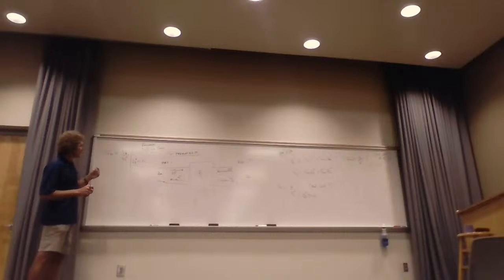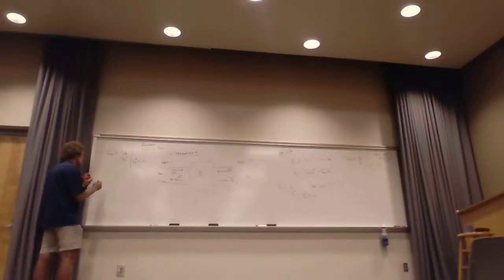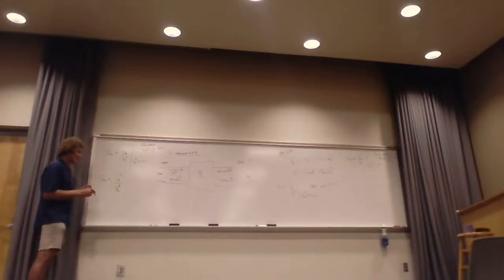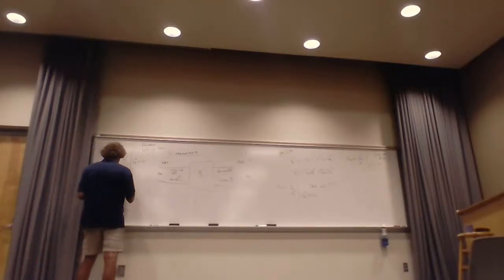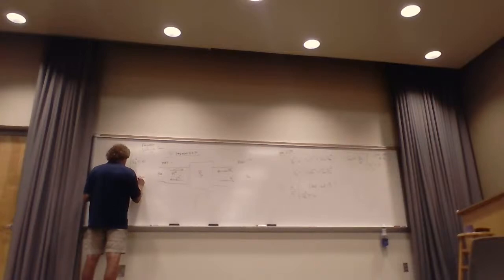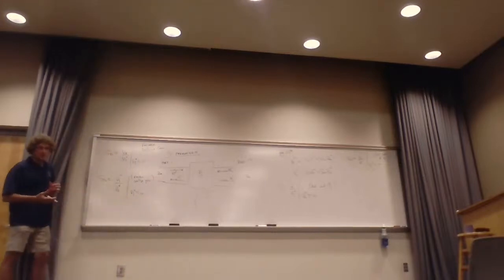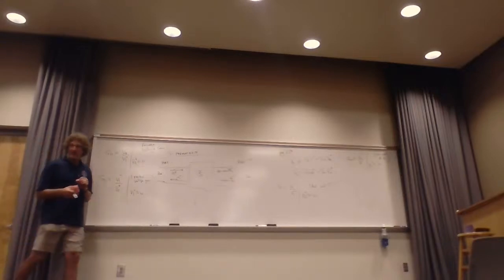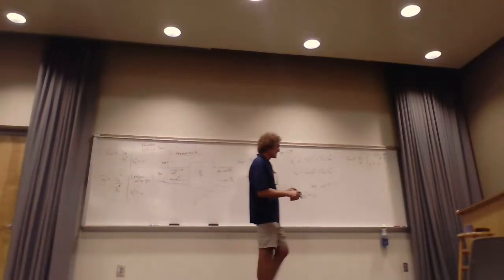All right. So anyway, that's the forward voltage gain, and the reverse voltage gain is really V1 minus over V2 plus, right? And that's with V1 plus equals 0. This is the reverse voltage gain. You don't want this. This is bad. You prefer not to have anything gaining. You would like this to be 0. That's the way it generally is. So that's what it is.